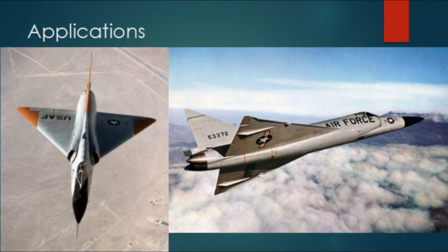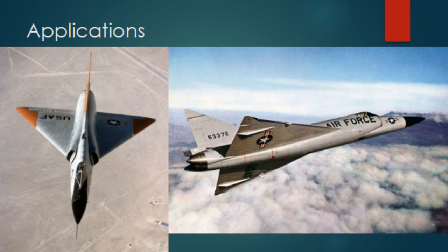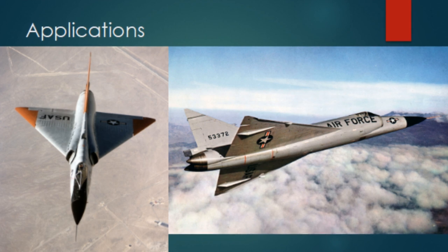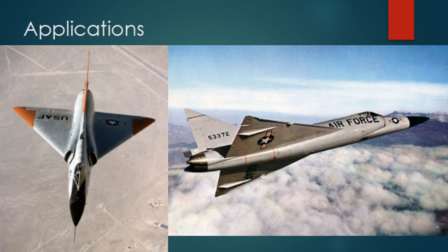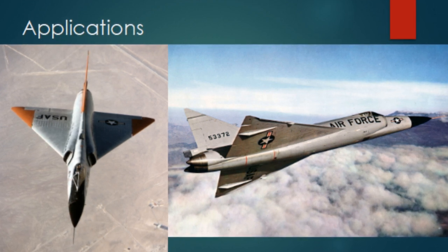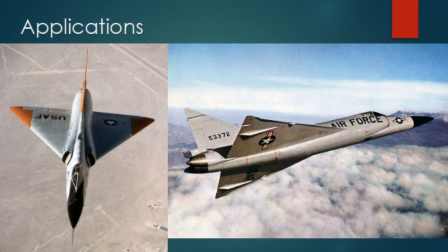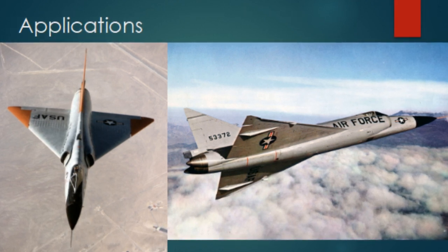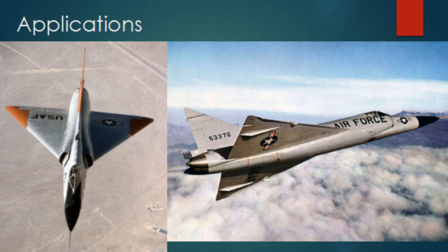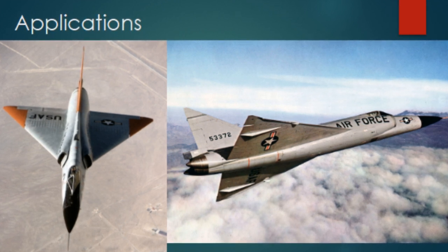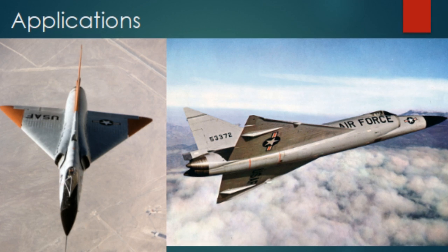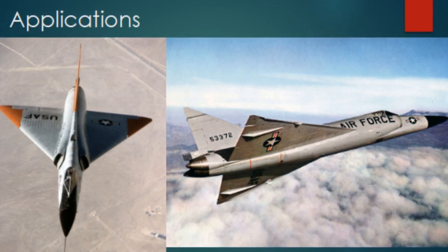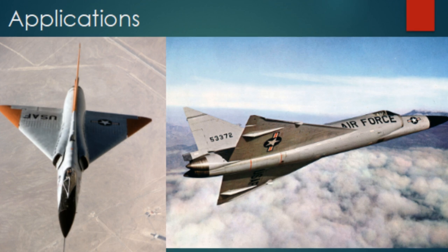Moving on to applications, the area rule was immediately applied to a number of development efforts. One of the most famous was Whitcomb's personal work on a redesign of the Convair F-102 Delta Dagger from the U.S. Air Force, which was a jet fighter that was demonstrating performance considerably worse than expected, by indenting the fuselage beside the wings and, paradoxically, adding more volume to the rear of the plane. Transonic drag was considerably reduced, and the intended Mach 1.2 design speed was reached.